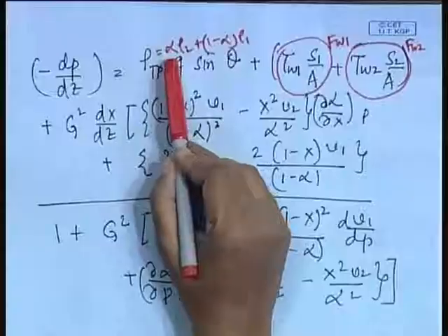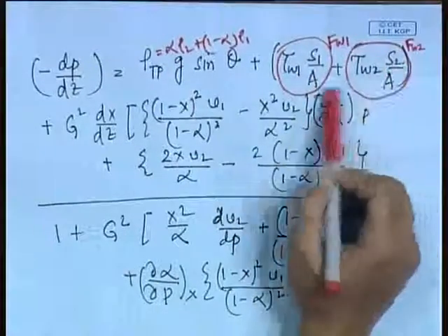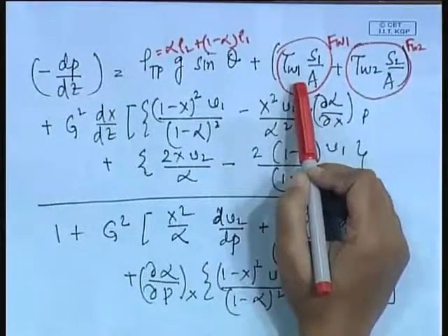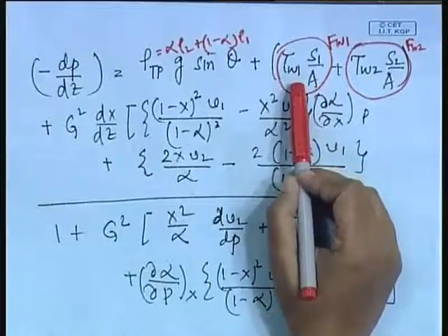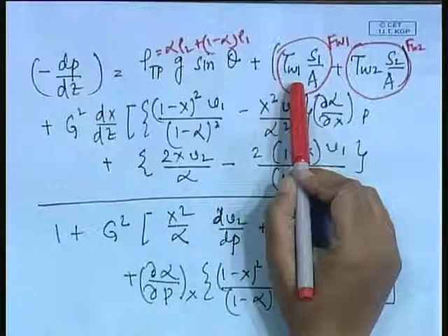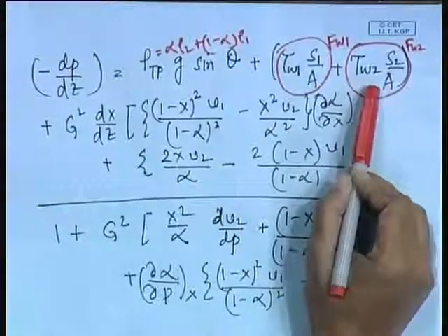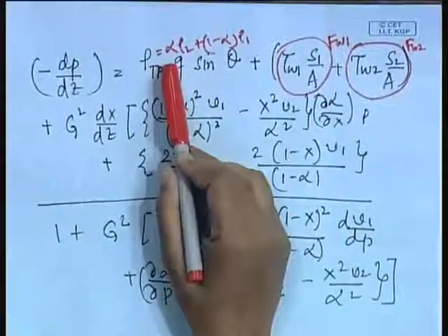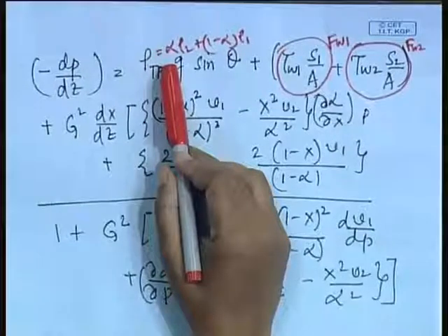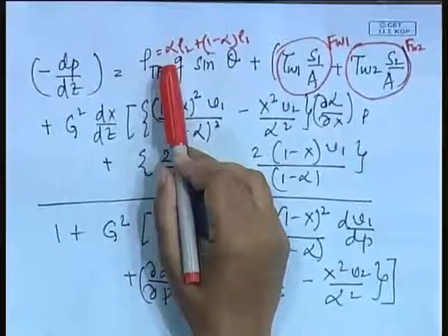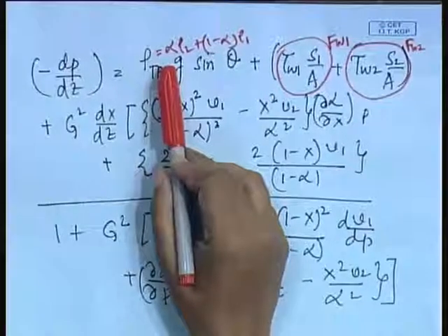So, usually for finding out alpha as well as the frictional component, a common technique is to use empirical correlations to predict the frictional pressure gradient as well as to predict the void fraction. And of course, certain simplifications come up. For example, when only one component is in contact with the wall, that happens for annular flow. Under that condition, we have just FW1, there is no FW2.